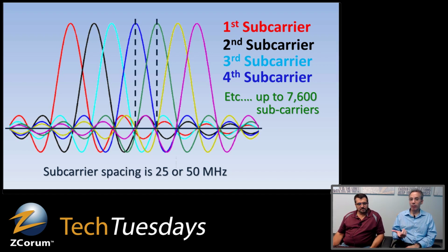But something interesting about OFDM, if you're going to roll this out, is you don't need to do it all at once. You can have your DOCSIS plant the way it is today, as long as you've got the frequency to spare. If you've got 192 megahertz or something in between that 24 and that 192, you can set up an OFDM channel, and you can have your standard carriers in other places. There's a lot of that shifting going on, people freeing up QAM space to put it in.